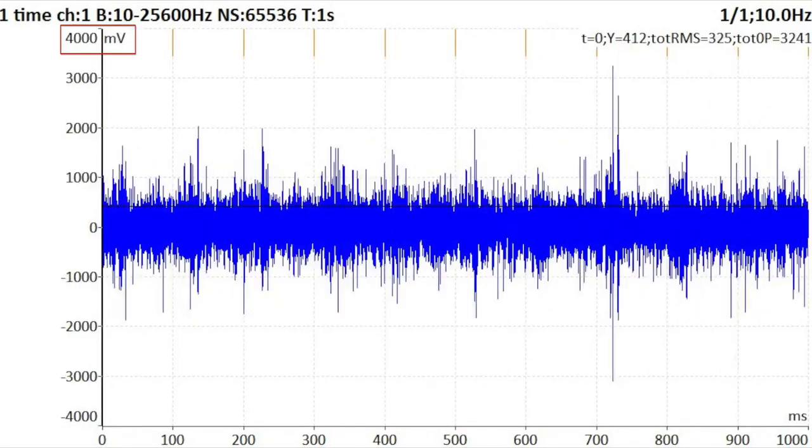This signal uses a gain of 500. Now the signal maximum is a quarter of the full range plus-minus 12 volts. That is what we want. Now 10,000 steps will be used. Such gain enables good analysis. How is it done in practice?